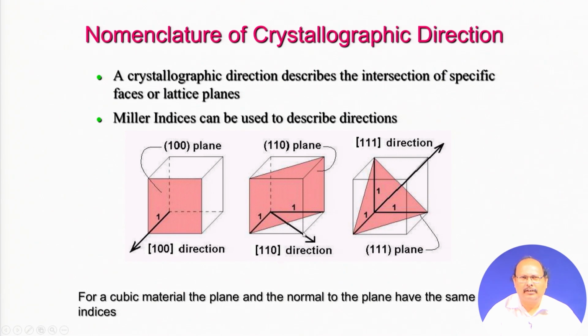If you think of this direction here, and we are at this point, what will be the coordinate along this axis? This will be this distance here, and along this axis this will be this distance. If this is of the same unit cell length, then this coordinate will be 1 1, and since the c intercept is 0, the nomenclature here is 1 1 0.